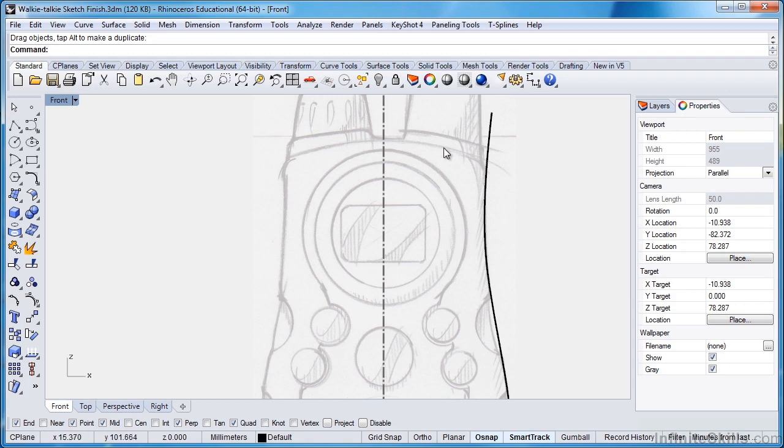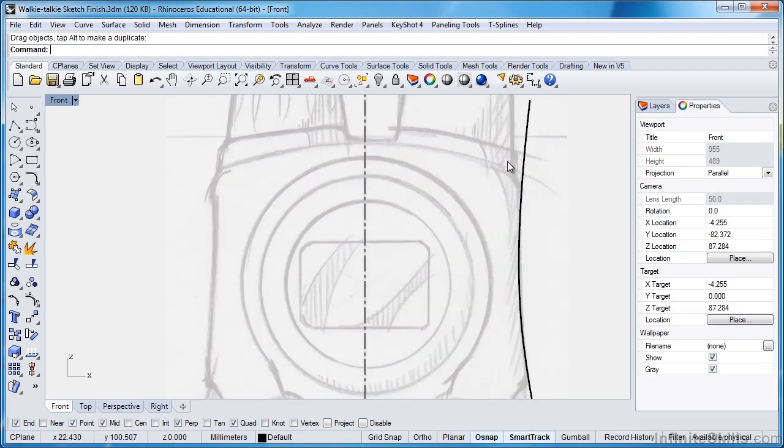And now I'm going to draw my curve that represents the line cutting across here, which is the upper surface. Now I'm going to ignore these because the little details we'll be adding later. And it's really this line here I'm going to concentrate on. So again, I'm going to use my control point curve. And this time I'm going to go down into my object snaps, and I'm going to switch on my near snap. Now I never have the near snap on because it just clicks on too many things. Notice if I put it on, as soon as I get near any line, it's just firing and snapping the things. And I find it gets in the way of things.